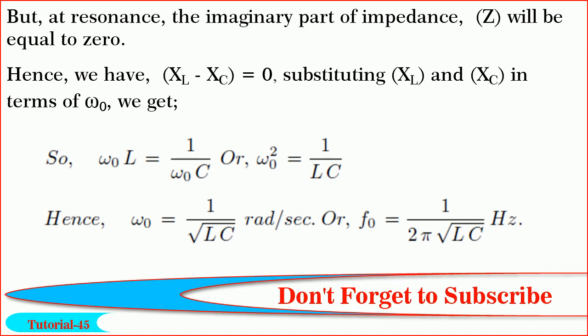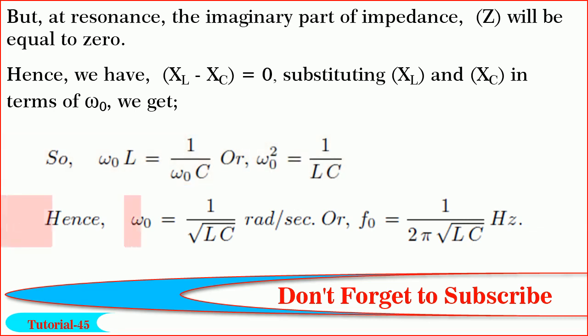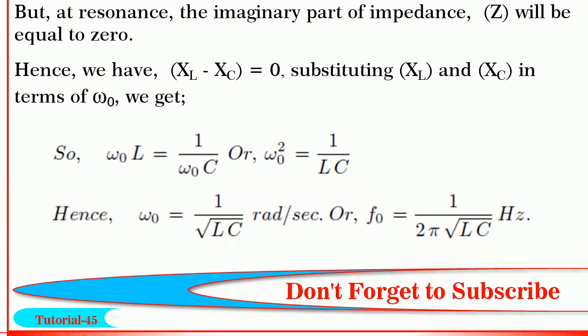But at resonance, the imaginary part of the total impedance will be 0. Hence, XL minus XC is equal to 0 or omega naught L is equal to 1 upon omega naught C, from which we get omega naught square is equal to 1 divided by LC and omega naught is equal to 1 divided by root LC radians per second, or f naught is equal to 1 upon 2 pi root of LC hertz. This is so simple, isn't it?